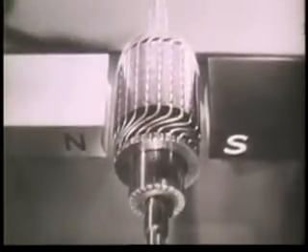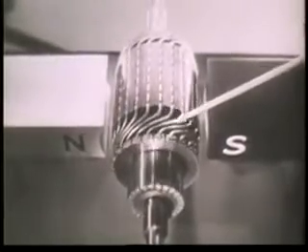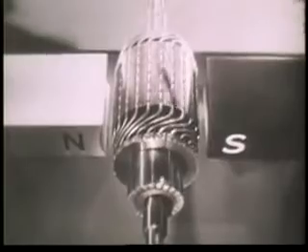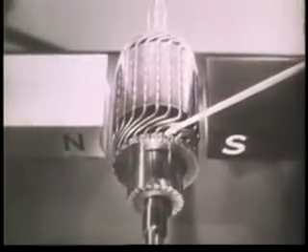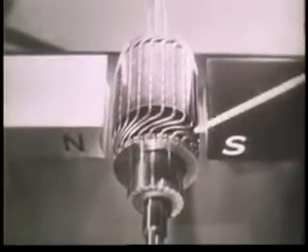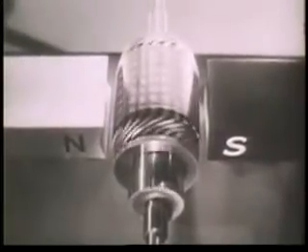The actual connections and arrangements of the windings are such as to allow a maximum amount of current to flow through the armature coils when they are in their proper relationship to the pole pieces. This allows each winding to add its turning effort to the others, so that they all work together to rotate the armature, as the complete assembly is called.